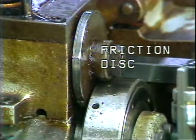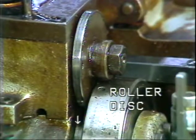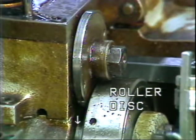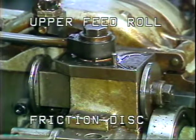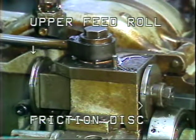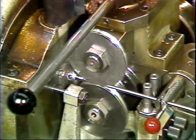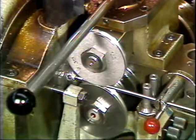When the upper feed roll is lowered, the friction disc will come in contact with this roller disc on the friction clutch assembly. The roller disc rotates with the friction clutch when the friction clutch is engaged. Pressure between the friction disc and the roller disc surfaces causes the upper friction disc to rotate. The upper feed roll will rotate with the friction disc. The lower feed roll is driven directly by the friction clutch. Rotation from both the upper and lower feed rolls cause the stock to be fed into the cutting tools and drills.